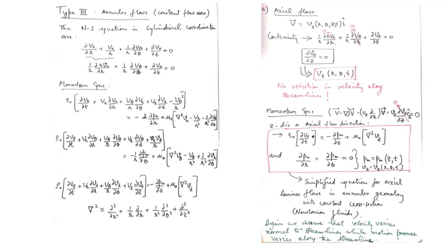So my momentum equations would become linear now, and I can write down the z direction or axial flow direction momentum equation first. So rho naught ∂Vz/∂t is equal to minus ∂Pm/∂z, plus mu naught and Laplacian of Vz.